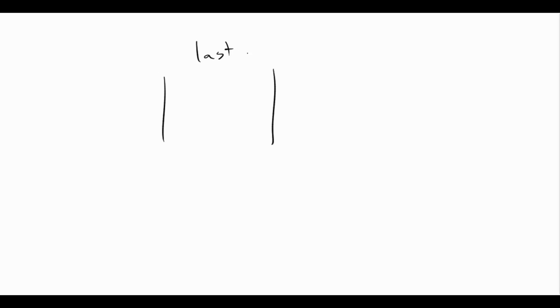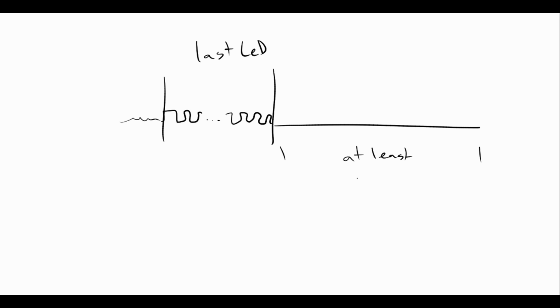When you're done assigning the values to the LEDs, you simply hold the clock line steady for 200 microseconds, and that tells the LEDs to reset and start the process all over again. Note that the values I've given are for the SK6805 EC14. If you're using a different LED, be sure to consult the datasheet.